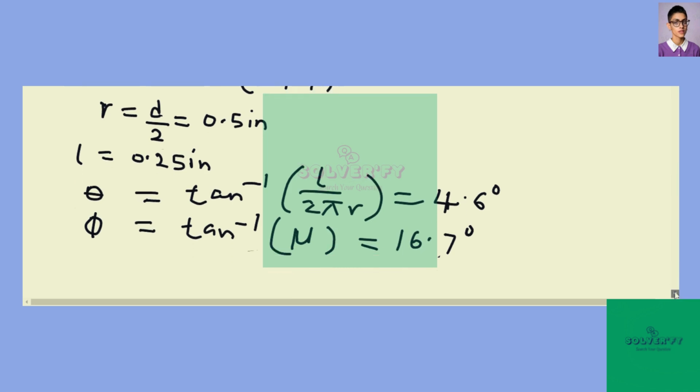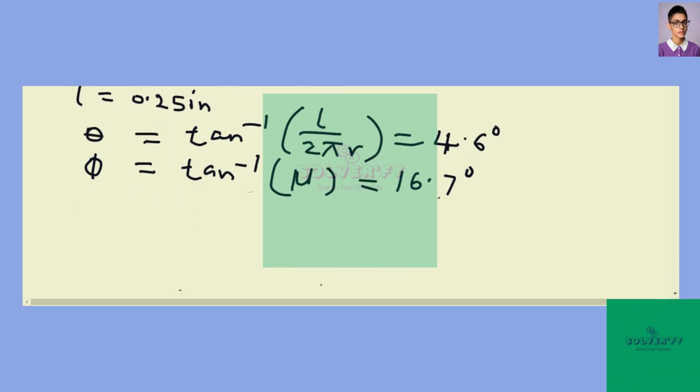Now we can look for the moment. The moment M can be gotten by multiplying the couple force, which is 10 lb, times the perpendicular distance given between the two, which is 12 inch. When you do this, you're going to arrive at 120 lb inch.